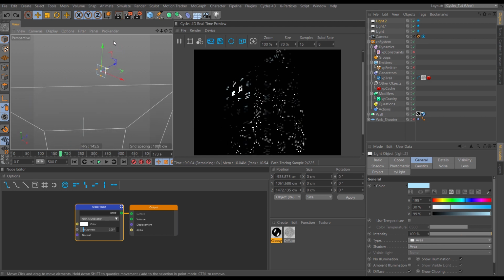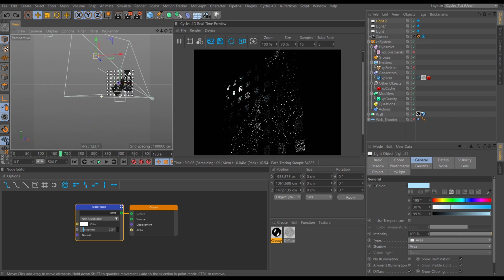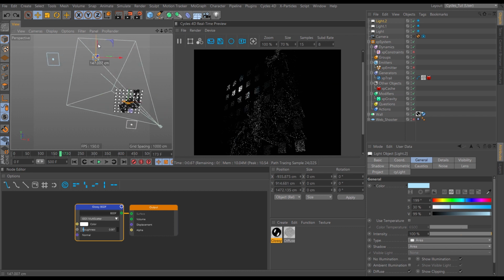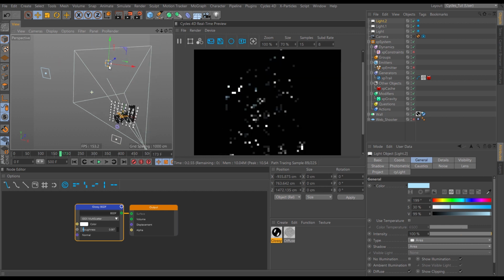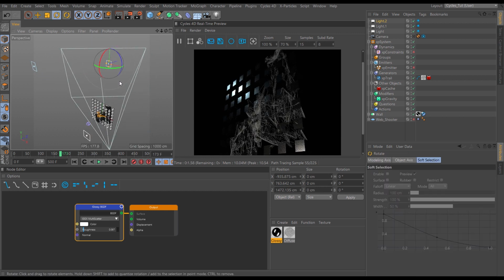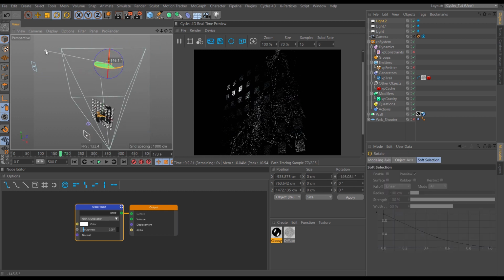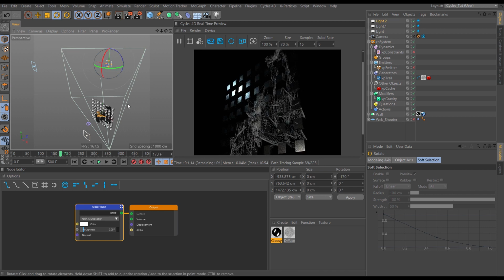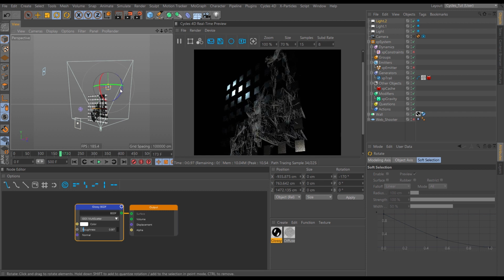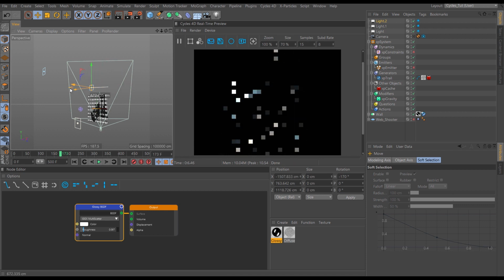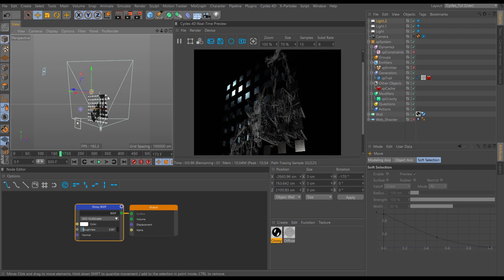So this one we've just made is behind, but it's facing the wrong way. Area lights in Cycles always point to the Z positive, so it's pointing away from our objects. Let's move it back that way. And let's just get an idea. So it's here. Here's our camera. That's way too far back.